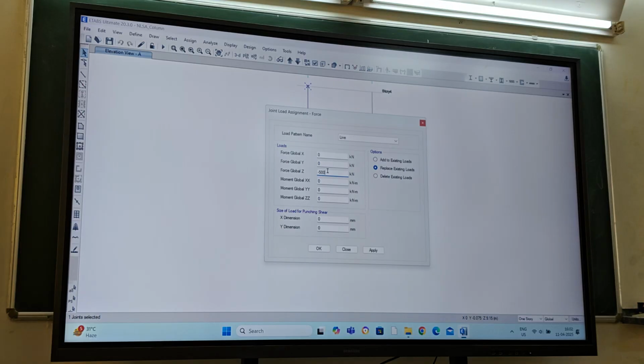One thing is the structure is too rigid, so it will not have the capacity to deflect much. Why does it happen? One reason may be high axial force, another may be that shear reinforcement is not adequate. Okay.